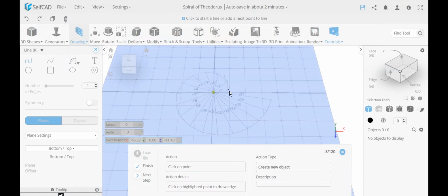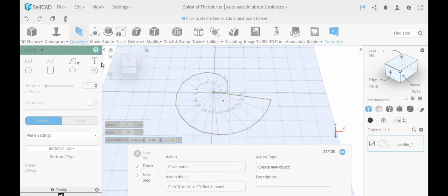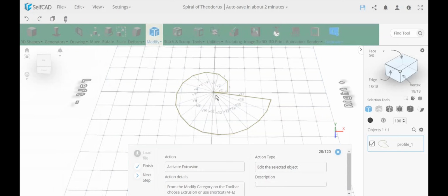We're not going to have to trace the entire thing. All I have to trace is the silhouette, the outline. So you can see we click over here and simply go over here. I'm just going to click next, next, next, next. As you can see, we simply go until the last, and when it comes to the last, we just snap it over here. Now, if you finalize, what we did is we drew a closed polygon, and I stress closed because that's the only way this is going to work. It must be a closed polygon.